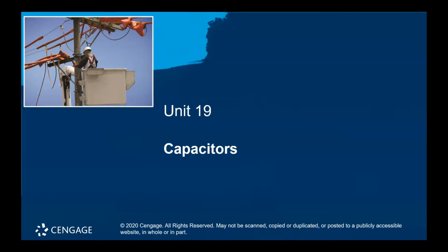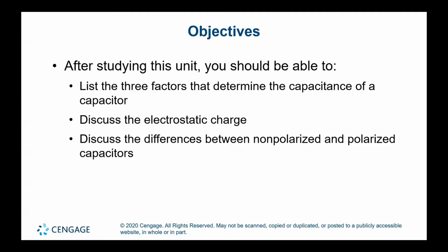The difference is going to be that in AC circuits, we are going to use non-polarized capacitors, while in DC circuits, we have to use polarized capacitors, okay? When we want to have a high capacitance in the circuit. And yes, we can use non-polarized capacitors in DC circuits as well, and you are going to be using those in the future, but they don't have as much capacitance as the counterpart, which is the electrolytic capacitor.